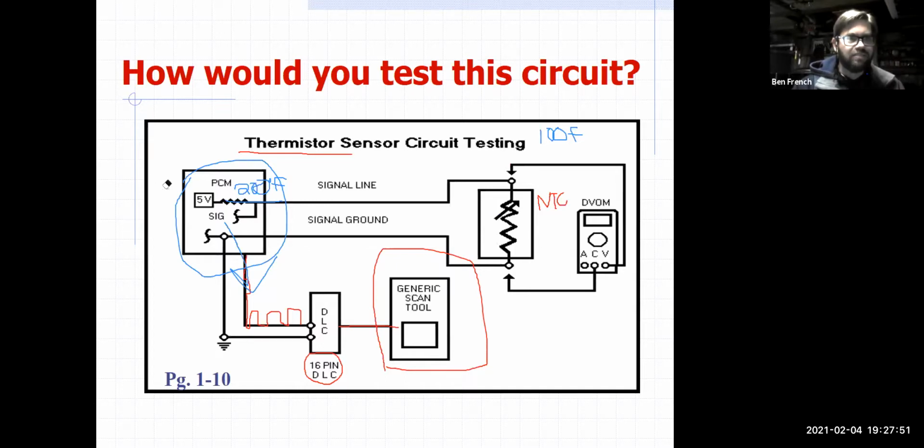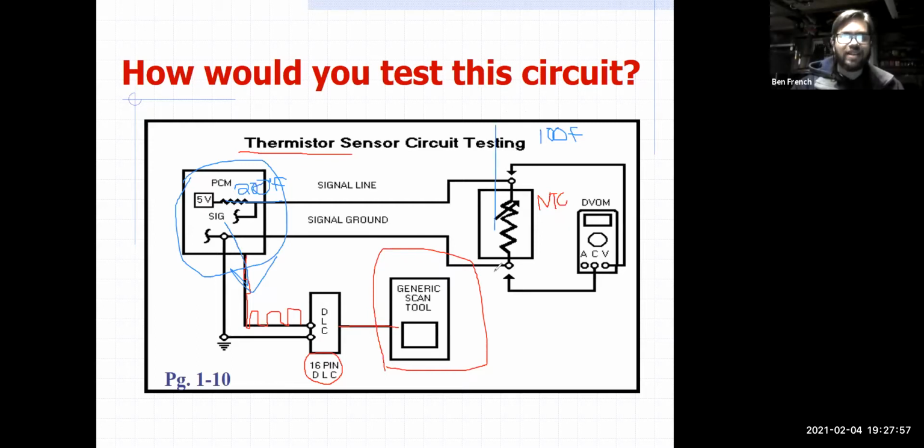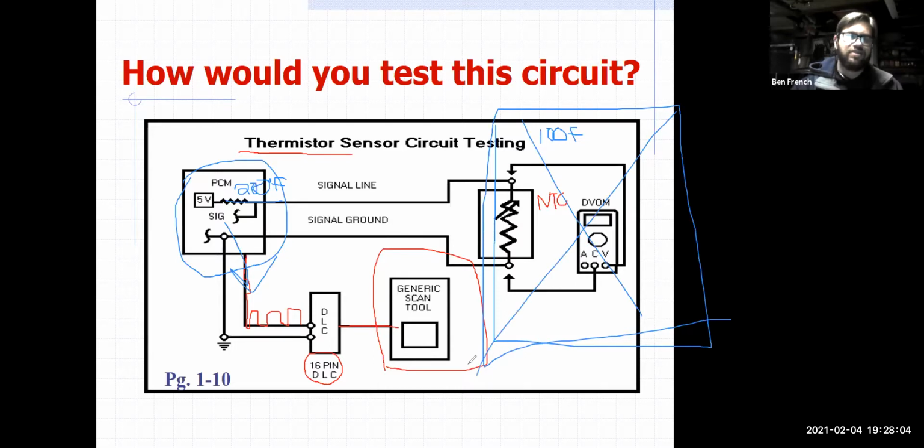Sometimes what would happen on cars, guys, is you might disconnect this sensor. In fact, that's one of my common tests for diagnosing failures, is I'll disconnect the sensor. And when the computer sees that the sensor is totally disconnected, he goes, what? Oh, there's something wrong. And then a lot of times he'll substitute values.